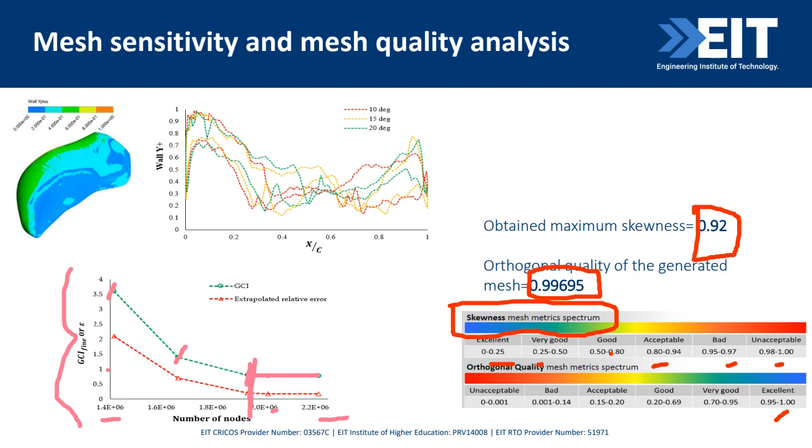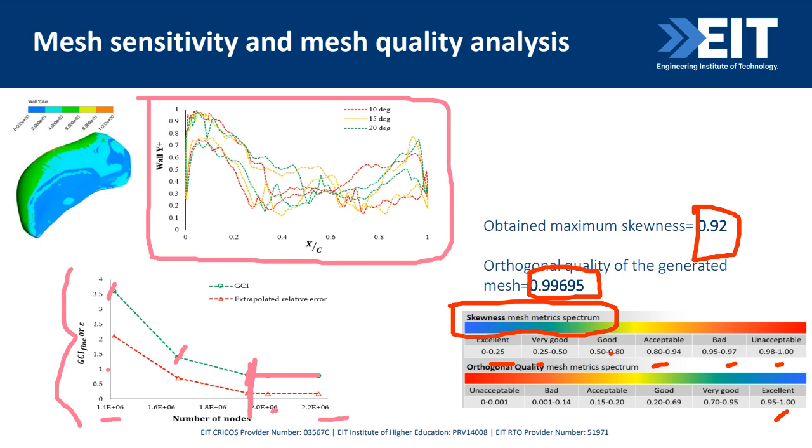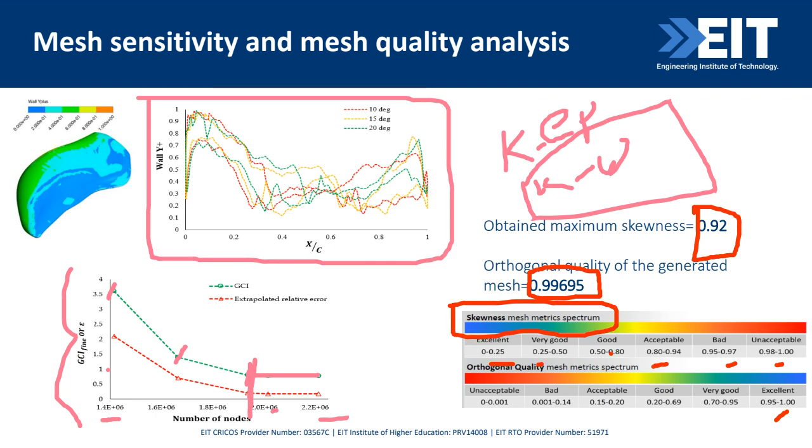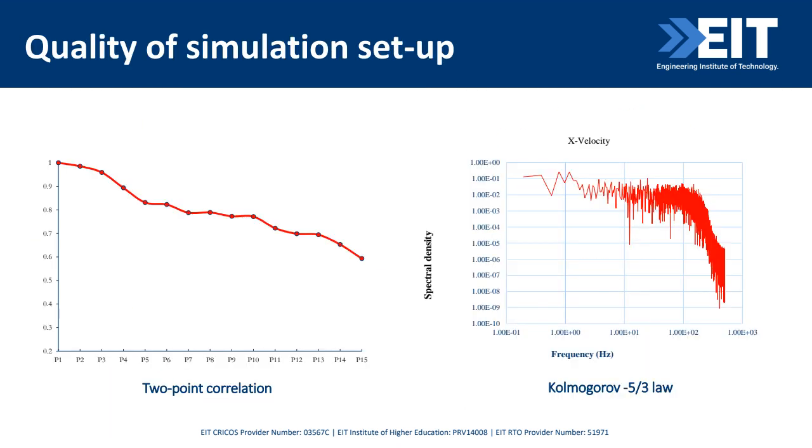That depends on the model that you will use. There are different models, k epsilon, then k omega, and there are also more powerful models that take more computational time. So different models demand different y plus. If I go deep into y plus, it will take more time. So just as a thumb rule, for the k omega model, we need a y plus over the aerofoil surface, or over any surface that we are studying, to be less than 1. That is the thumb rule that you need to follow. So that is all about the mesh and 2-point correlation.